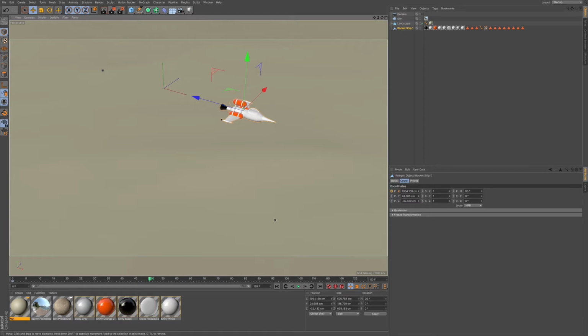What that's telling you is that this object has been moved, but it hasn't been saved yet. Whenever you see that orange circle, you know that I moved my object somewhere within 3D space, but that position hasn't been saved yet. In order to save that, you'll have to command click on the circle. Now you can see this keyframe, and now you have your animation.